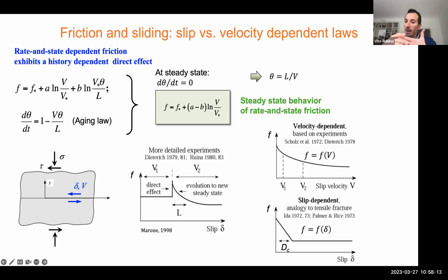Now, on the outer surface you have a plane-stress-like stress state. It's not really plane stress, but the out of plane stress is zero, and so out of plane shear stress components are zero, like in plane stress.